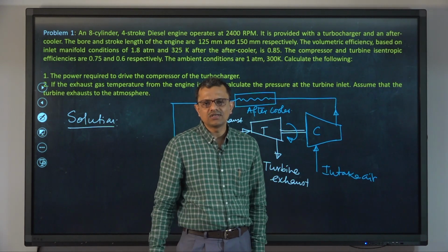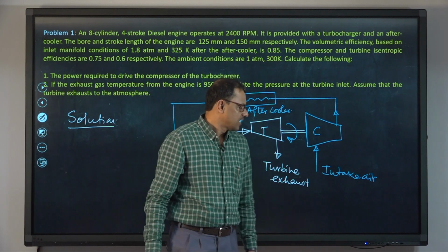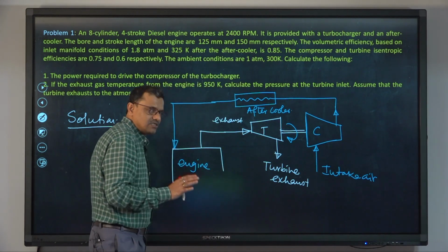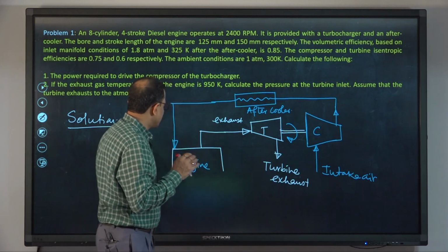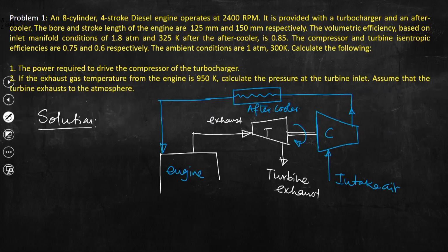So, that is not a desirable phenomenon at all. So, what is done is this particular unit, that is the after cooler, is incorporated here to reduce the temperature of intake air before it enters the engine.